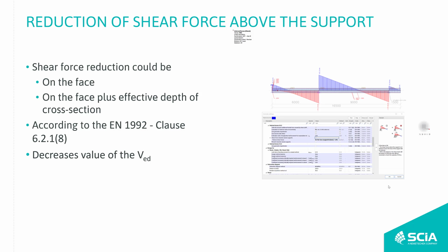I can go to the concrete settings, think here that I would like to reduce shear force above support, and I have the option that it could be on the face or on the face plus effective depth of the cross section.